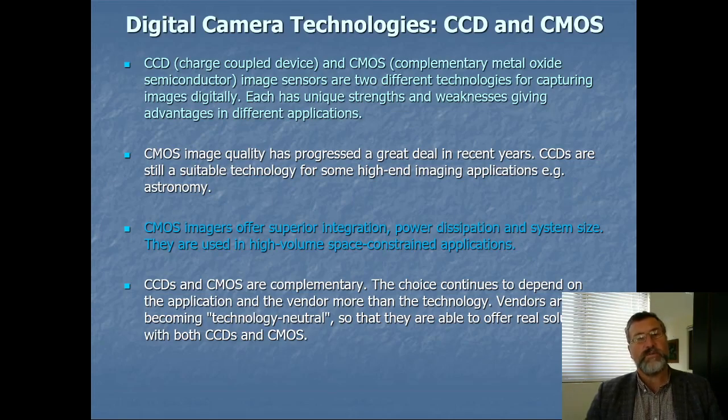Another thing that's important that is often not mentioned is the size of the actual sensor. If you look at something like a digital SLR camera, you'll have quite a large sensor in it, because they want a nice, good quality image. Well, we want that in machine vision too. So a larger sensor with bigger pixels means you get more light going in, you get a better signal-to-noise ratio, and you get a better quality image. Generally speaking, you won't need such a small focal length on the lens, so you'll get less distortion as well. But of course, it costs more.